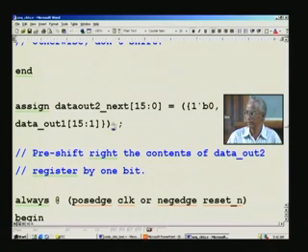So, this does precisely the same thing as that one, and it has been named 2 just to distinguish it from that. When we simulate, we can easily compare the two and see that it is basically the same. And this is the concatenation of 0 for the MSB, that is the bit vacated, and shifted on the right here. So, 15 bits here plus 1 bit here, in total it makes 16 bits, that is precisely what is here.